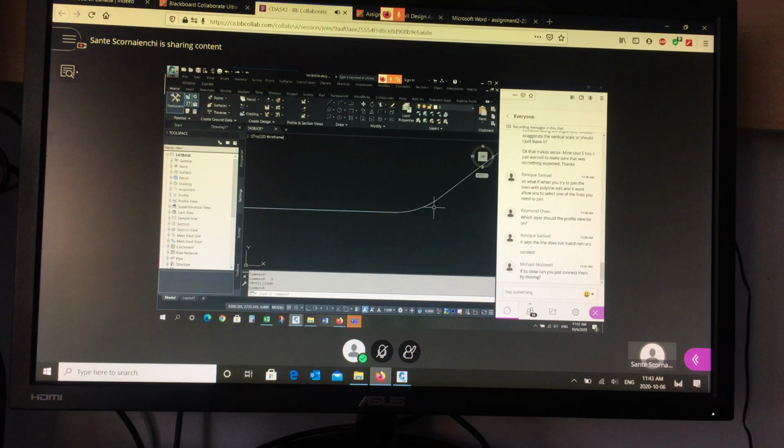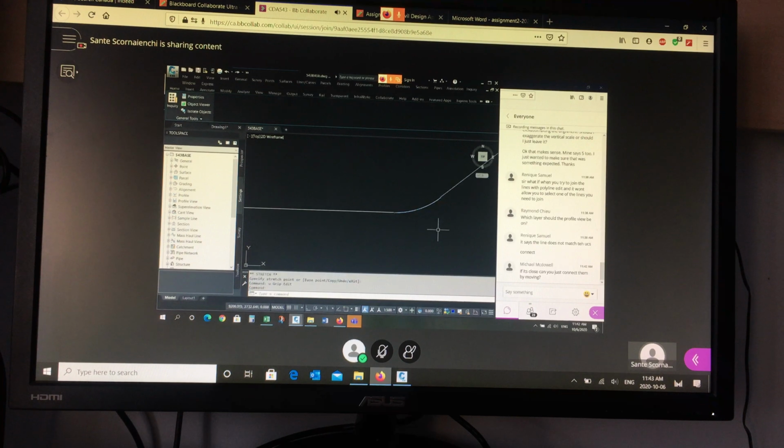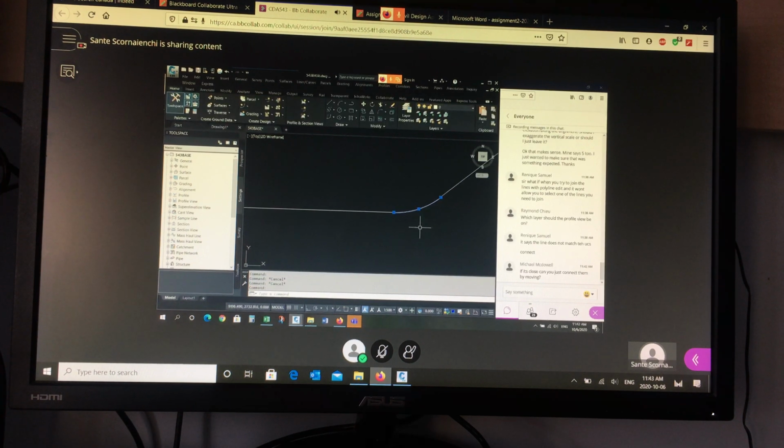If the drafting is sloppy, if this is not in the right spot, let's say it doesn't match, then what I would do is note the radius, 10. So I'm going to delete that, and I'm going to fillet with a radius of 10 and redraw that one entity. So there's a couple of different ways of doing it, depending on how small that gap is. So it's a judgment call, and it depends on what it is you're drawing.